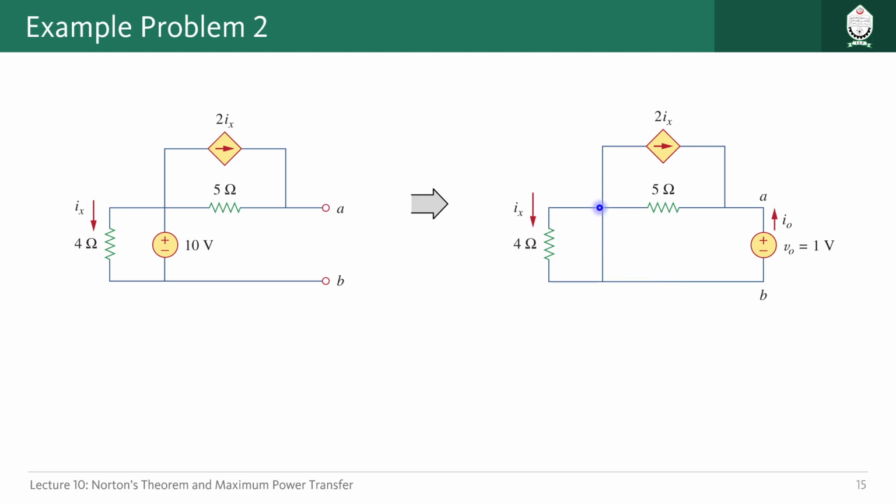again, we can think of these two parallel paths here. This path has a resistor, but this one is short circuited. That means all the current should flow in this path instead of this one, as they are in parallel with each other. But before that we have to calculate the value of Ix, because this dependent source is dependent upon this current Ix. So easily we can say that the value of Ix should be equal to 0, as we had earlier discussed, right?